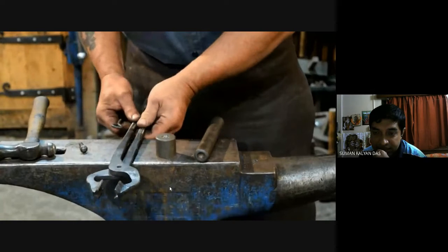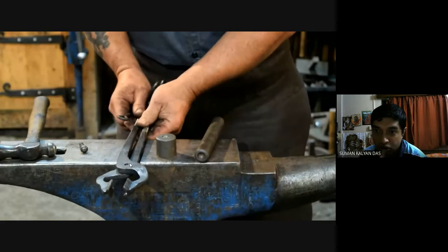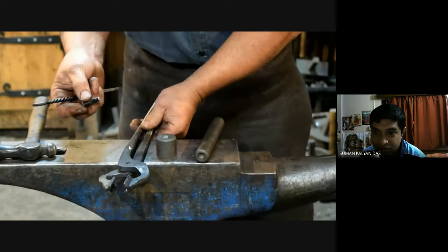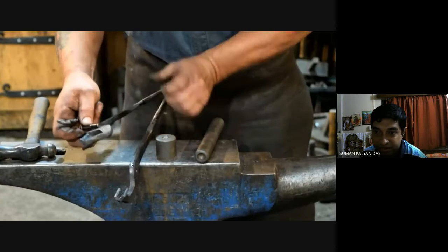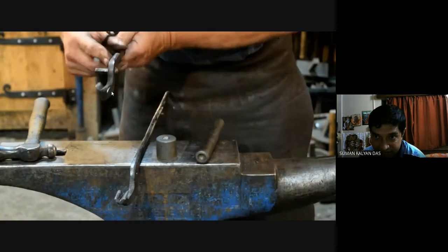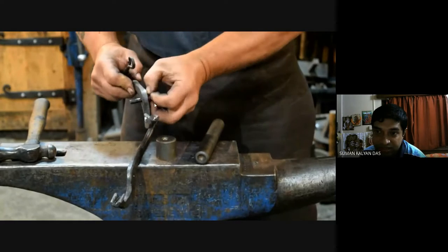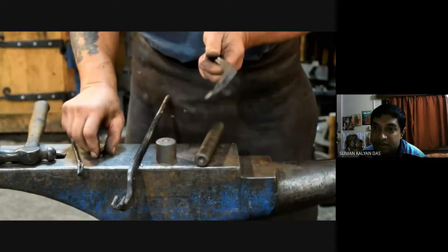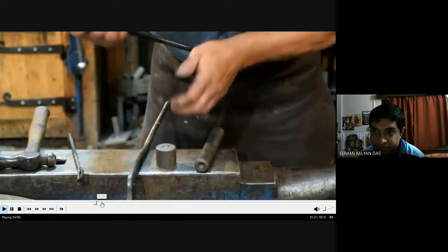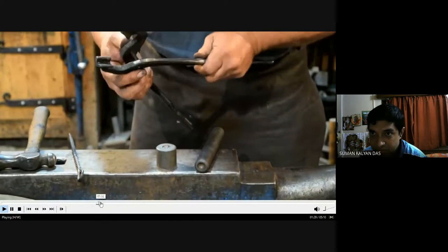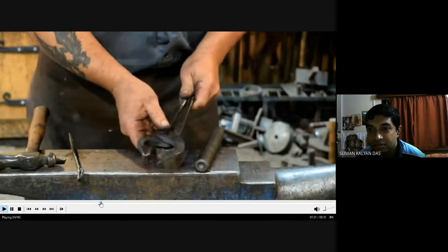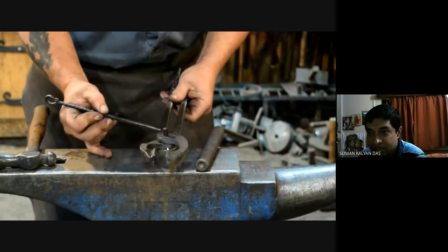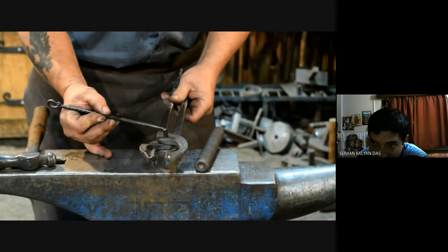And this is the tongue, a pair of legs that he needs to attach with the help of this rivet so that the tongue can be utilized. Right now they are separated, so that is what he is planning to do. So you see, he inserts the rivet and fits the head on the backup bar.